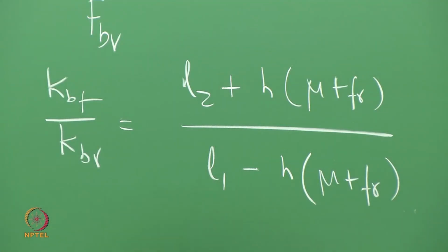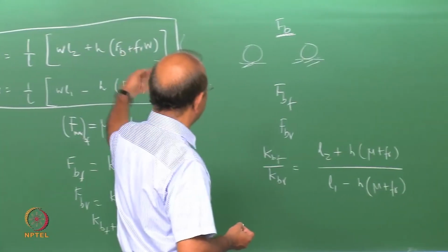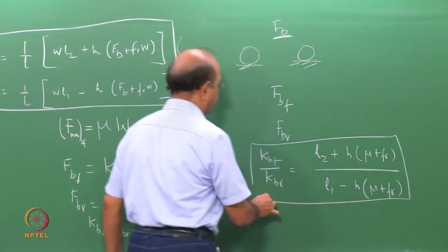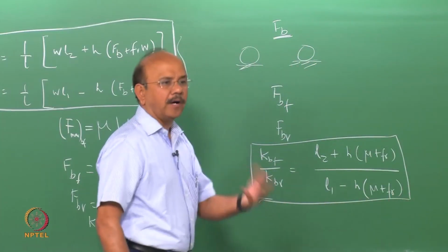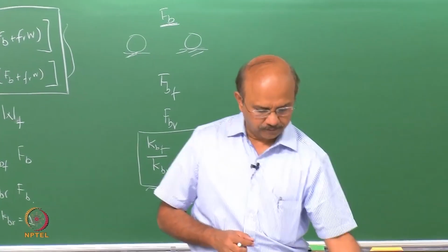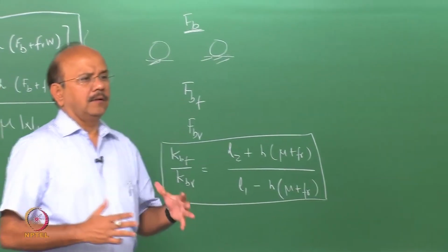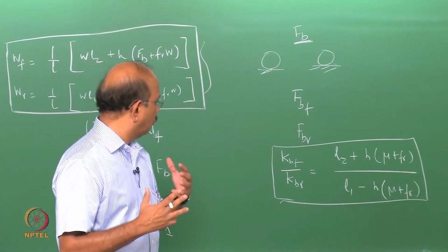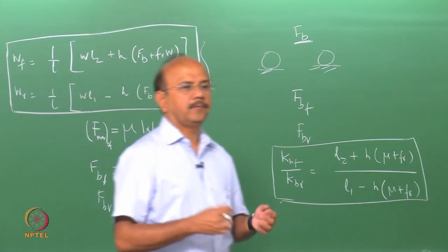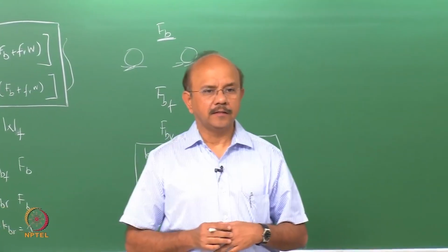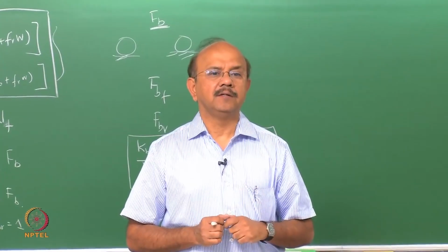Okay. So, if the two forces are distributed proportional to Wf, which I have just rearranged in this fashion, then that is an ideal braking where both the front and the rear would brake at the same time. Typical values for this would vary from one vehicle to the other, and even for the same vehicle it would vary.